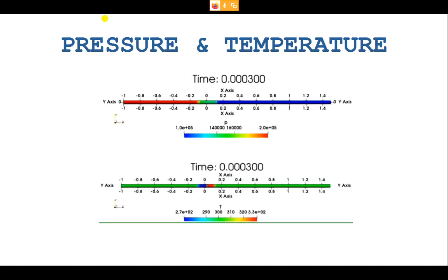And this is a typical visualization with respect to time, showing how the pressure and the temperature vary. What our group did is, the simulation was made to do the transients, and the post process was recorded as a video and then converted into a GIF, and the GIF is played here. At time t equals 0, the shock tube is intact with the high pressure zone on the left and the low pressure zone on the right.